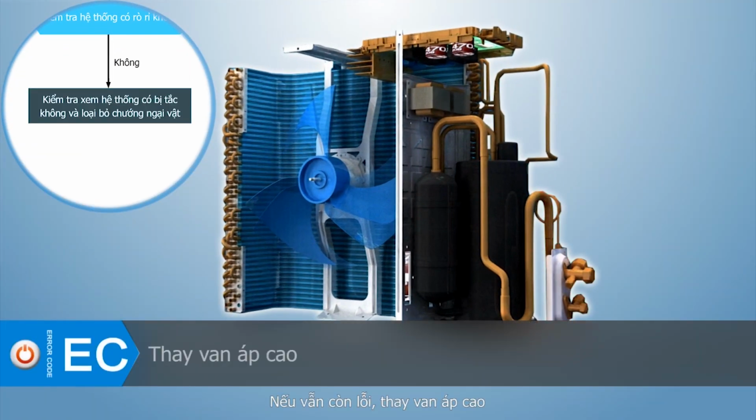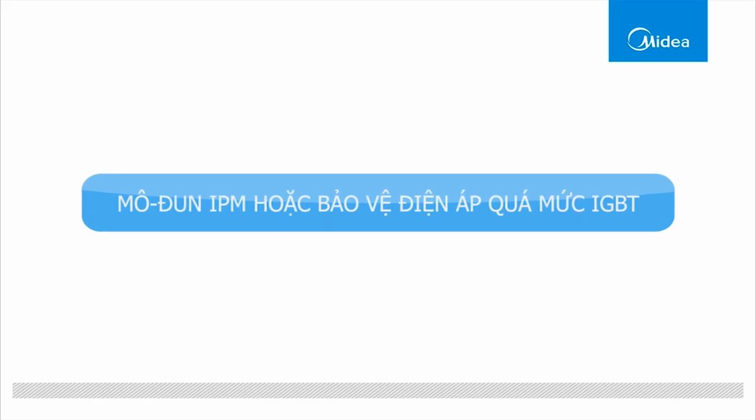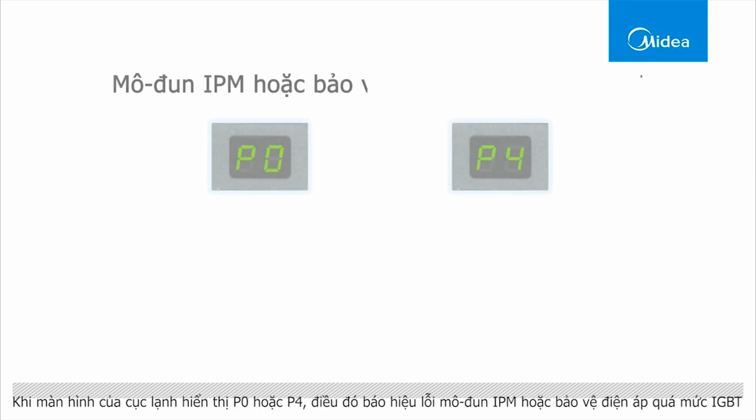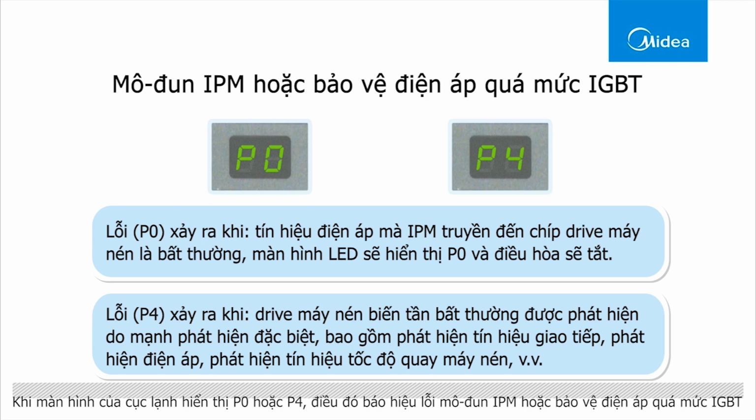If the error still exists, replace the high pressure valve. When the indoor unit displays P0, P4, that indicates IPM module fault or IGBT over voltage protection.